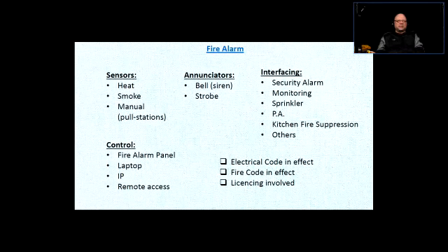And usually 99% of the time, the only sprinkler that is going to be activated is the one that is affected by the heat. All the other ones are not going to spray water. It's not like in the movies where you break one of them and the whole system goes nuts, spraying water everywhere.